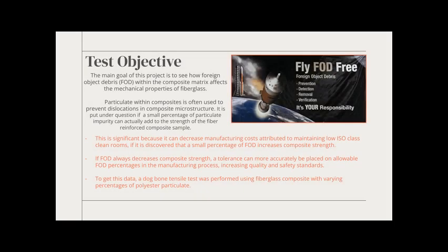With this project, we tested to see how foreign object debris, or FOD, within the composite resin matrix affects the tensile properties of composites. This is to answer the question, does adding a small amount of FOD actually strengthen the composite? This is plausible because particulate reinforced composites tend to prevent dislocations in the composite microstructure. Hybrid fiber particulate reinforced composites are common in the aerospace industry, but will FOD particles have the same effects?